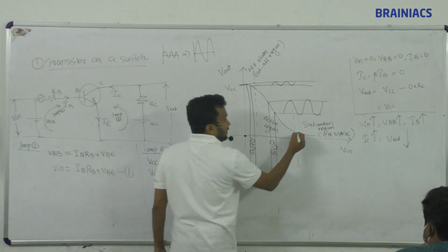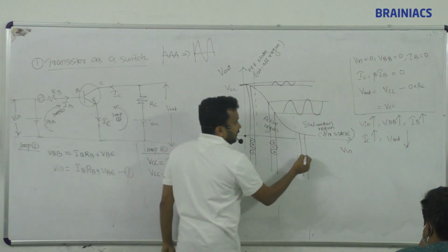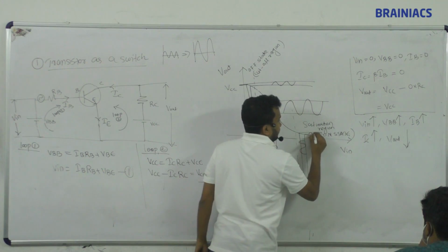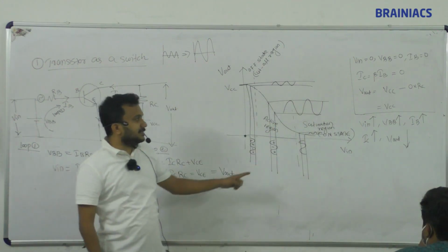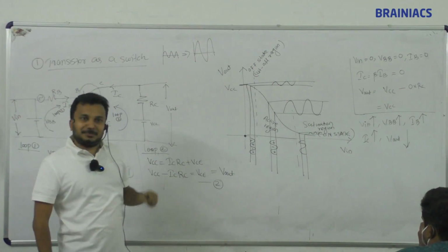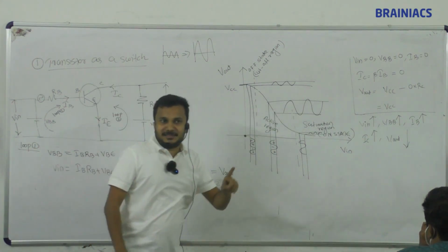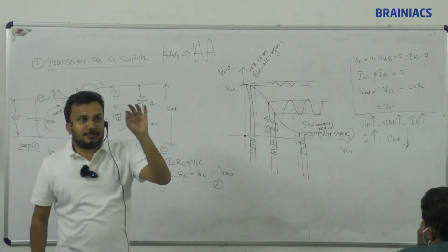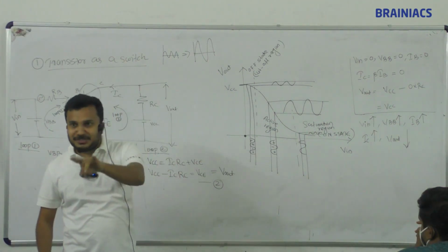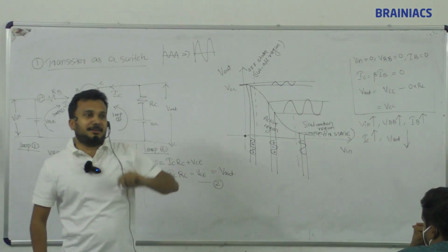Now suppose the transistor is in the saturation region. You have taken two points and you are giving an input signal similar to this one and you got the output like this. So what happened here, the size reduces or is more or less the same size. Okay, it depends upon my drawing. But one thing is sure, definitely in the active region it gets amplified. So the transistor will work as an amplifier in which region? Active region. The transistor will work as a switch in which region? Cutoff region.